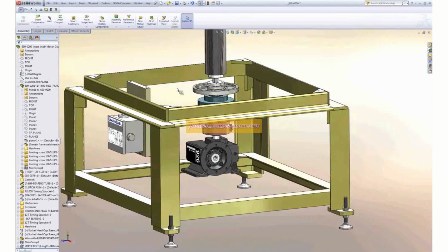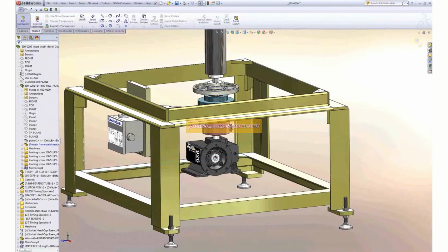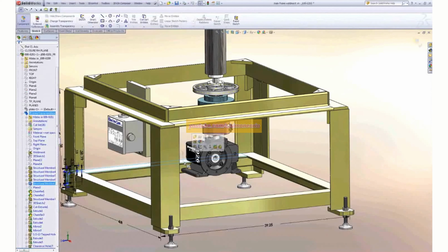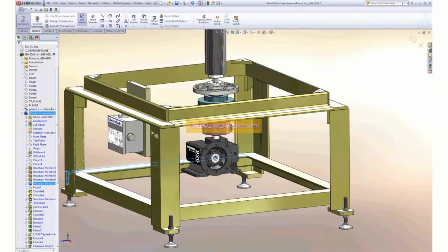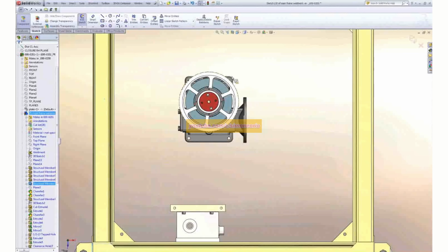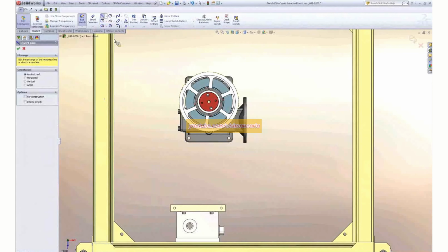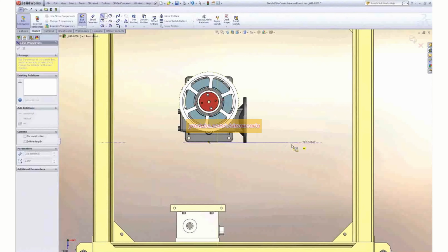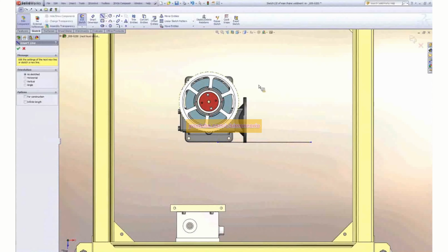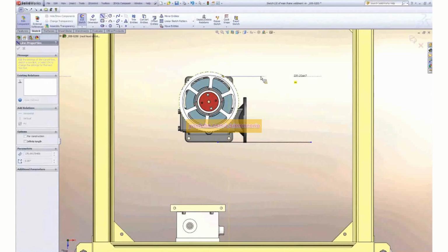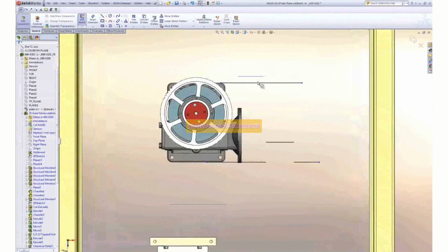So what we're going to do is just throw in a couple weldments to hold everything into place. So I'm going to go ahead and add it to the base plate that we have right here. We're just going to make a couple modifications to this part to enhance the way it looks here. So I'm going to grab a sketch and flip over to my top view here because we're actually going to inference the gearbox. So I'm going to go ahead and grab a sketch tool, and we'll just draw in a couple lines for our weldment profiles.